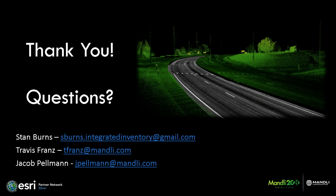Stan, I think I can jump in. Yeah, go ahead, Jacob. Yep. I think they're just curious about the instrumentation. It sounds like they might have just jumped in late. So to collect the pavement data or perform the pavement inspection, we used the LCMS, LCMS2 pods by Pavemetrics to collect the pavement data. So that did the bulk of the automated distresses. And then for any of the more nuanced distresses that couldn't be taken out automatically, we used those same downward 3D and 2D images to help rate any manual distresses too. So hopefully that answers that question.